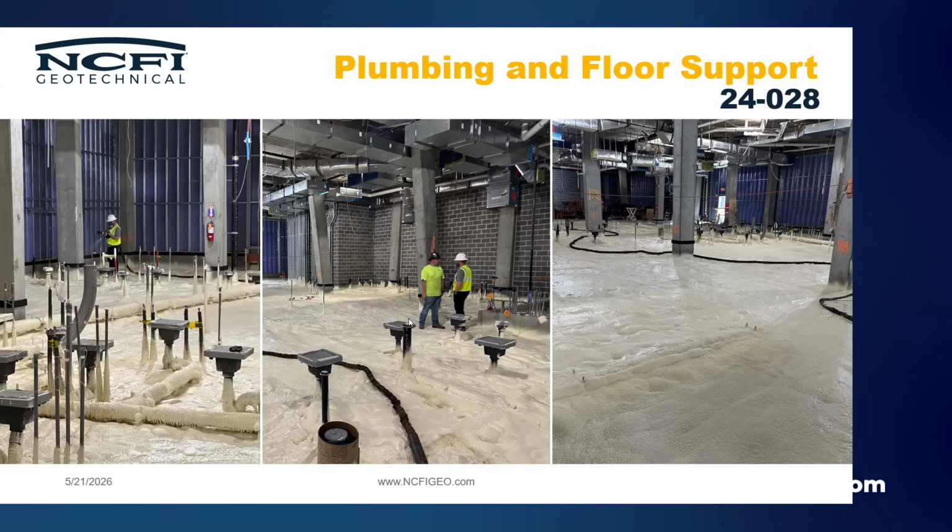You can see that door in the far right picture. The threshold for that door is 3 feet above what the original grade of the concrete was. They wouldn't allow them to put the plumbing through the floor down into the parking garage because they didn't want the penetration there, and they didn't want to lose the clearance down there. So everything had to be built on top of the slab, but the slab could also not support filling this in with gravel, concrete, or even cellular concrete. It needed to be something super lightweight.